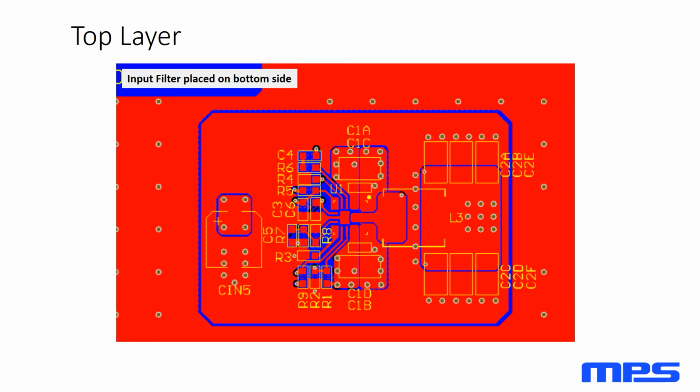And if you take a look at the manufacturer's information on that particular capacitor, they should show you a Z versus frequency plot. Sometimes that's a way to help you select which components might be of use to you if you're trying to target very specific things. This tends to get into power integrity discussion, but typically smaller is going to be better in terms of parasitics and its performance at higher frequency. Larger is going to be more towards the lower frequency side in general.